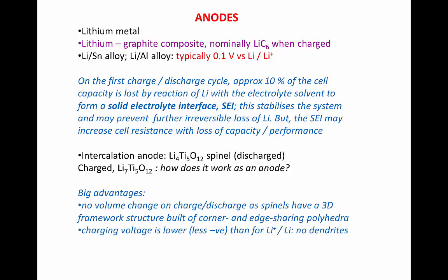And this is a serious advantage in lithium batteries, because one of the major problems is disintegration of the electrode-electrolyte interface, if you have an electrode in which there are large volume changes during charge and discharge, because this causes a fragmentation of the nice interface between electrode and electrolyte. So the small volume change is a big advantage in such cases.